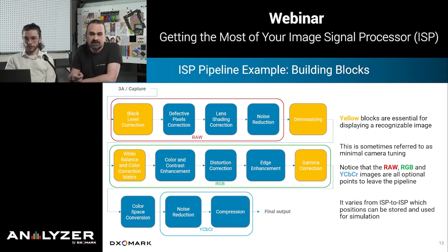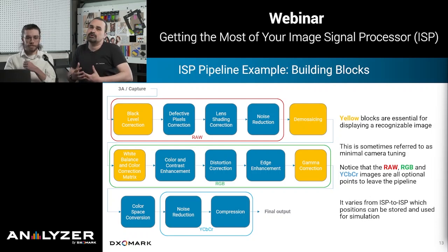For this reason, some corrections are very nicely applied at this stage, because everything we do after that tends to be destructive, so you cannot recover the information. This is the moment when you have maximum information. At the same time, these are specific to the particular colors of your Bayer filter and a higher number of bits per sample. So maybe the algorithm needs to be a bit heavier. So you're not going to be able to do everything in RAW for a variety of reasons.